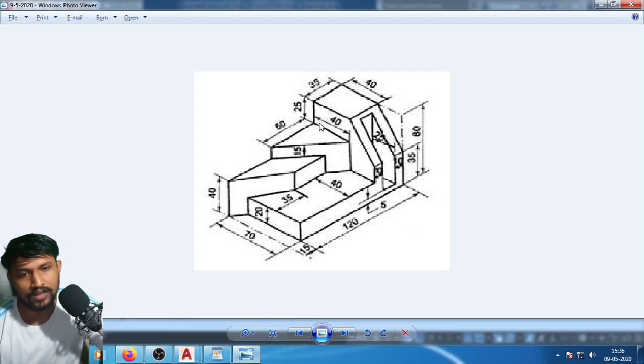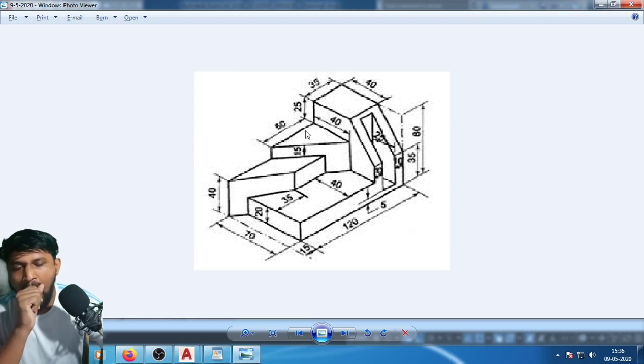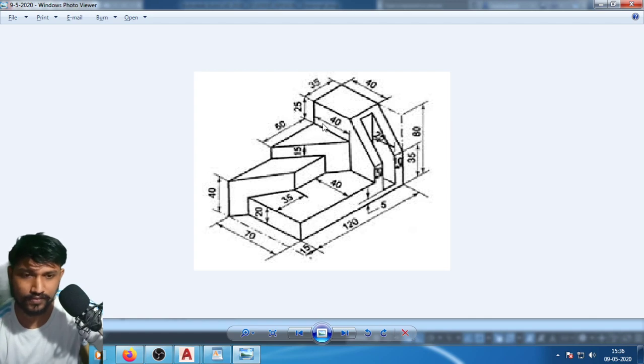So here, in order to create this extruded triangular face, I was given these dimensions 30 by 40, and here the height has to be 15. See here, this particular height is 20, which means if the total edge dimension is 40, and this dimension is 20, this height is 20, right? 20 plus 15 is 35, right?